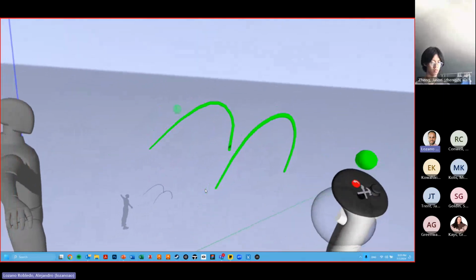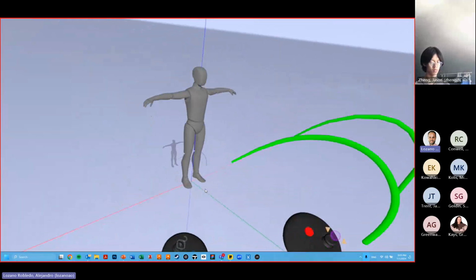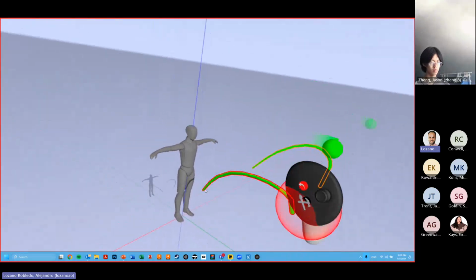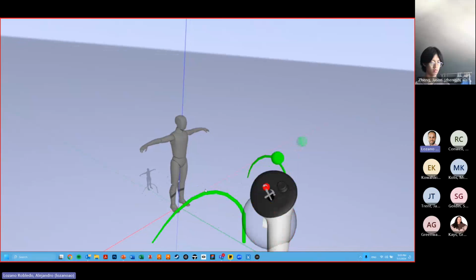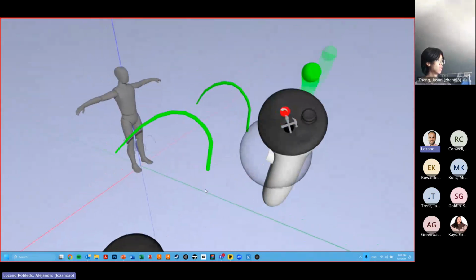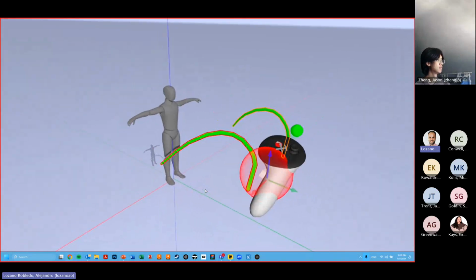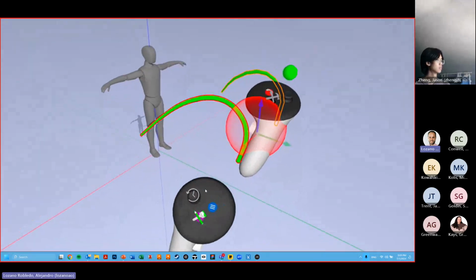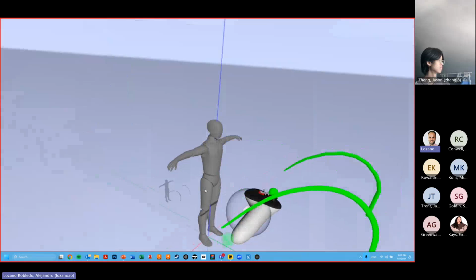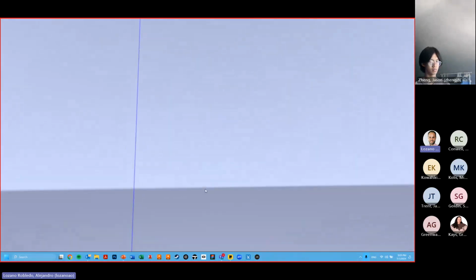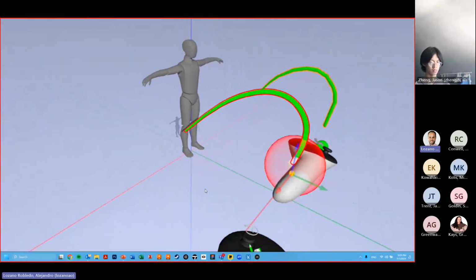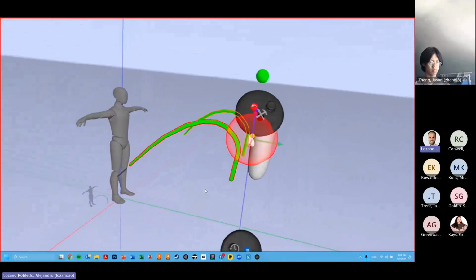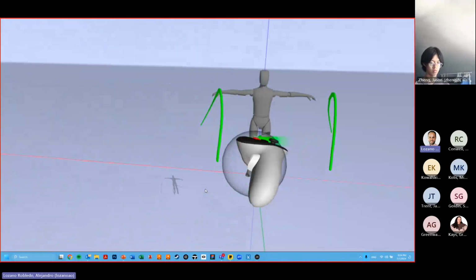And something more advanced that I'll show you later, which is extremely important, is how to move things accurately. Because if I just move this, I have no clue how I'm moving it or in what axis. Something really cool is if you are hovering over an object, and as you can see, there's an axis that shows. If I align my 2 controllers according to an axis, so look at how, in this case, I'm aligning them according to the red axis. Look at this red line that appears. If I'm aligning them to the z-axis, the blue line appears, and same with green, right?